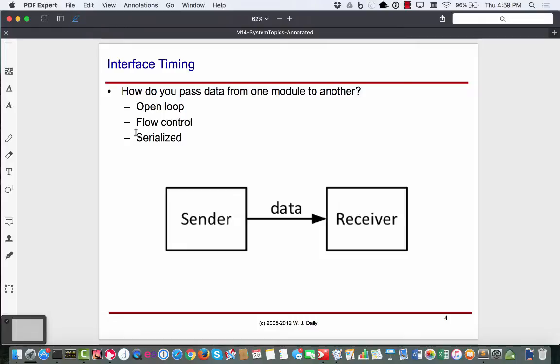When I have a parallel set of wires running, I put a bunch of bits on them, my 32-bit word, and then that 32-bit word traverses over the wires and reaches the other end. At the other end is a register, and they're going to clock it in. I have to make sure that all those 32 bits traverse with roughly the same delay.